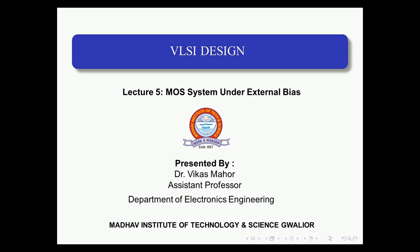Only the MOS structure, not the MOSFET. Please understand the difference between the MOS structure and the MOSFET. Until now, we have not studied the effect of voltage or the internal band diagram of a complete MOSFET, that is, the structure consisting of drain and source. We have just studied the energy band diagram of only the MOS structure, which consists of a metal gate, silicon oxide, and a silicon substrate.